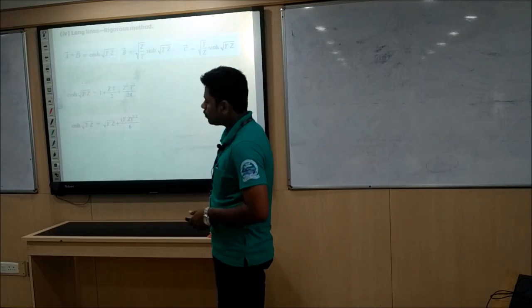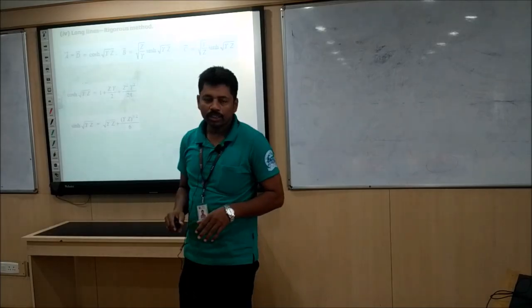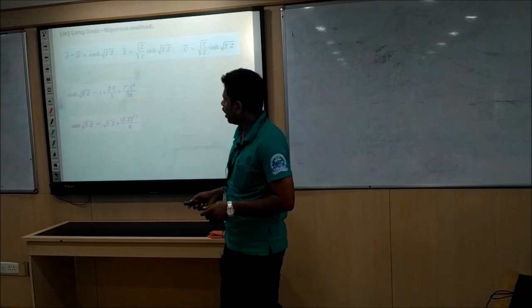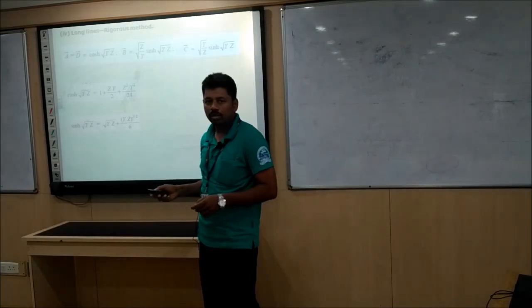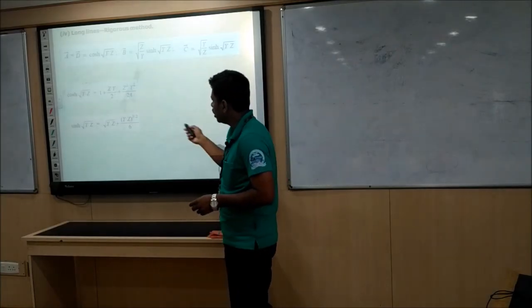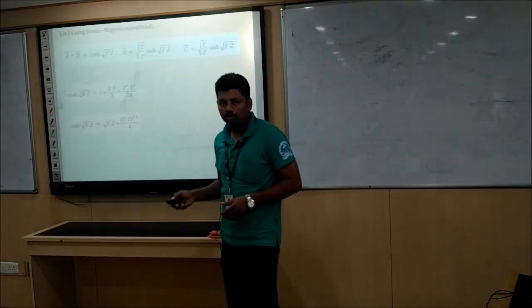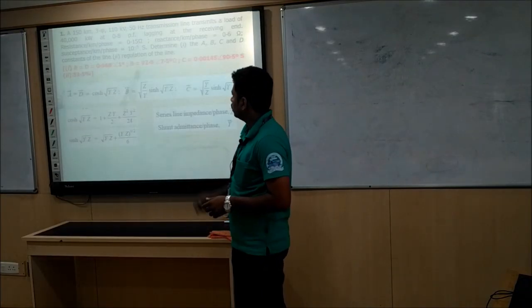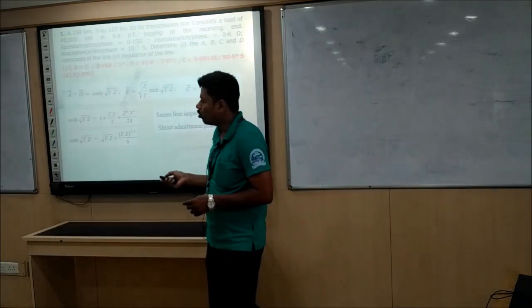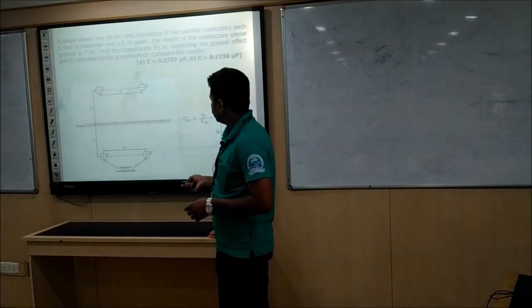In the long transmission line, the equation is already of the form Vs equal to A VR plus B IR. If you compare, A equal to D and AD minus BC equal to 1, all those conditions give you the expressions. That is why we can use this for the long transmission line also. There are some numericals which we are not going to discuss now, just to apply how to find the voltage regulation and efficiency for the various cases.